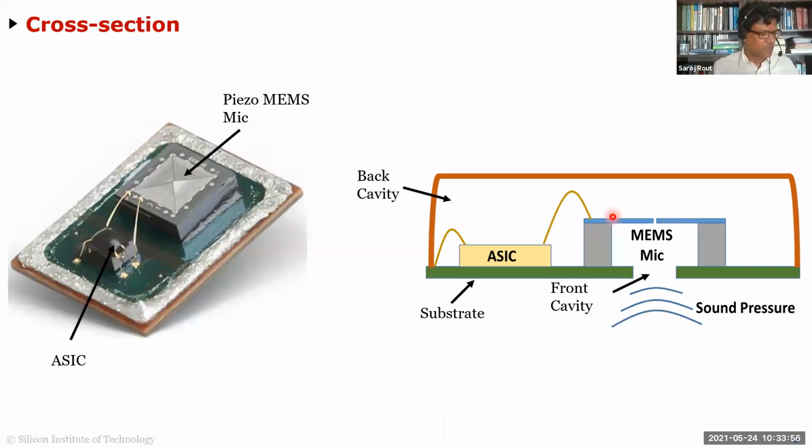When you speak, the sound waves move these piezoelectric devices, and piezoelectric devices, as you know, convert strain into voltage. So that strain is getting converted into voltage. That voltage is converted by this integrated circuit into either analog voltage or digital. Most of them are digital, so there is an analog to digital converter here as well, and it'll send you out the digital signal. So all your webcams, your cell phones, your laptops, wherever there are microphones, they're typically these microphones.